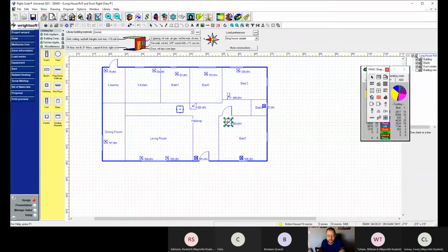So normally I would like to match my load that I got coming into the room to the load coming out of the room. So if I got 155 coming in, I don't really want to pull 500 out. You know what I mean? Because then you're taking more out of that room than you're pulling in that room. So I don't know if this is going to let me select that or not. I'd love to be able to set it to a matching CFM, but right now it seems like I must be doing something wrong, or must be missing something probably.